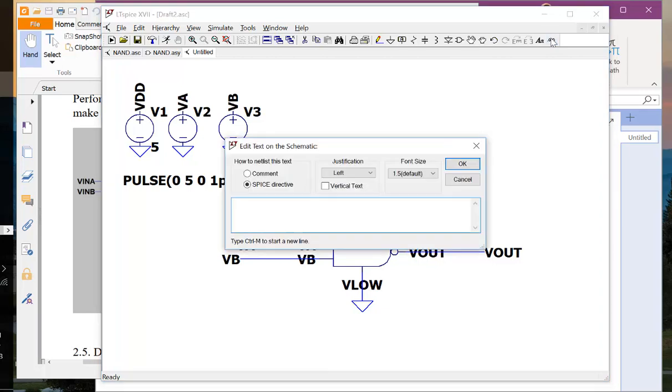Okay, and we got the power supply, we got signals, and I think we need a SPICE code. So let's do a transient analysis. So the x-axis is time, and because we have 20 microseconds for each period, let's just run for 100 microseconds. We're going to get 5 periods in there. All right, and also don't forget to include the model file. It's called model.txt. If you have a different name for it, you just use a different name.